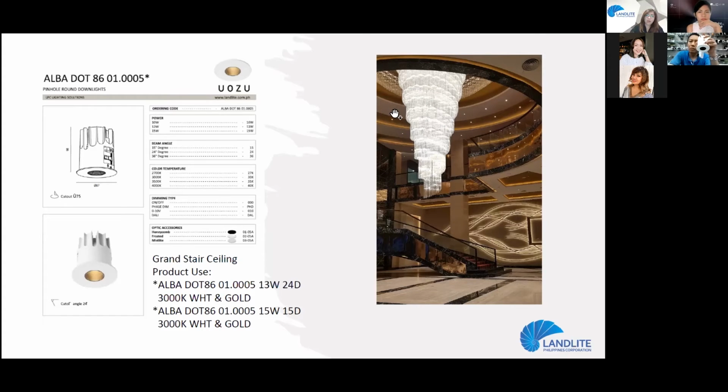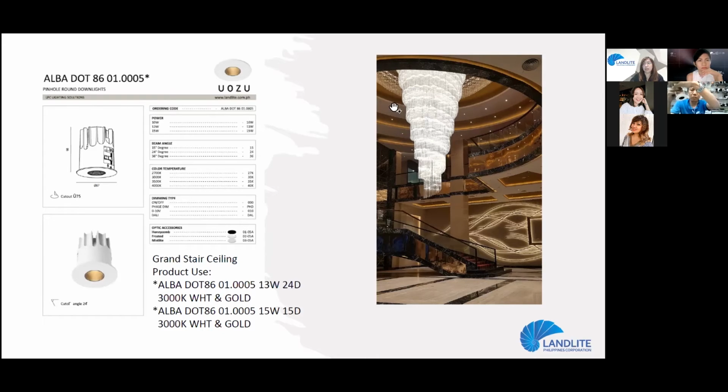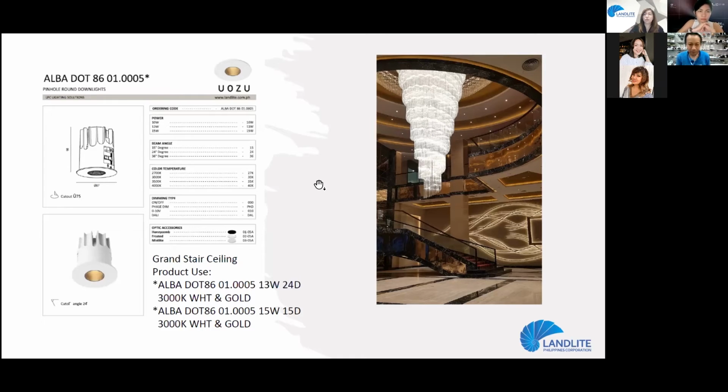Continue. Okay. Now, why did he use 13 watts? Number one, because it's going up, he needs a transition of light, so the light needs to be softer. Why 24 degrees? Because the area is shorter, so the circle created by 24 degrees is bigger. So that's what he used for the grand staircase.